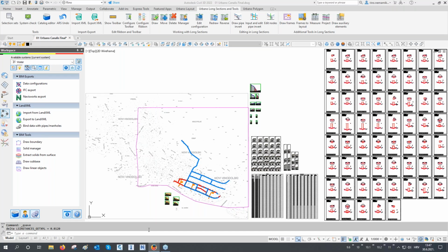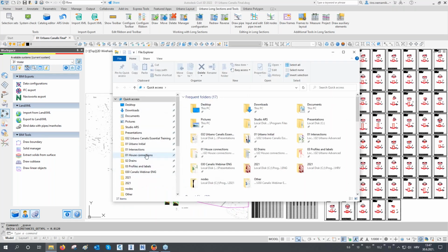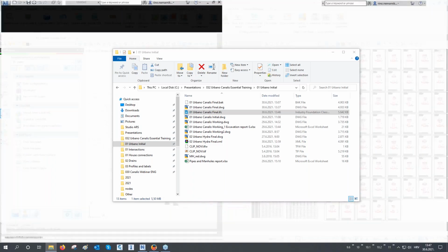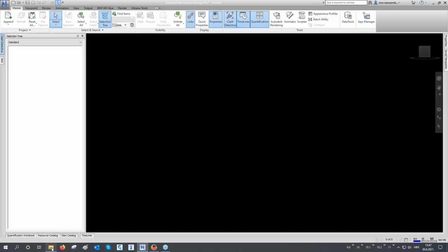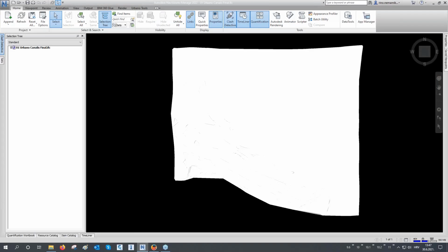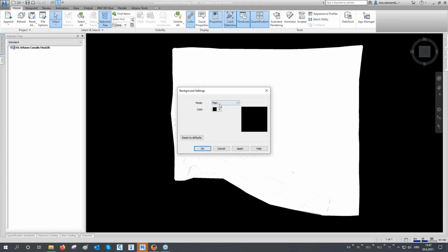Okay, let's now check our IFC file because we exported it. So it is located here. Here it is, the IFC file is here. Let's open Navisworks or any other BIM software that you are using. I use Autodesk Navisworks. So just drag and drop it. If you are using Navisworks, then maybe it is better to go directly through the NWC file. You have some advantages, but some investors always require this IFC file. So it's up to you what you will give to them.